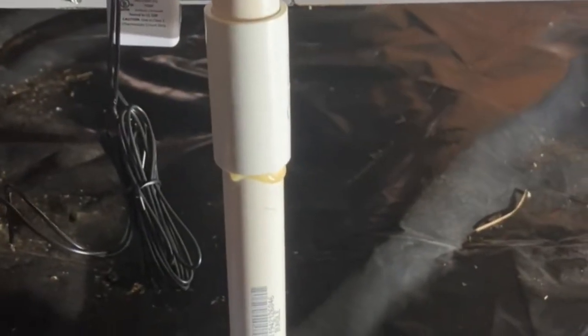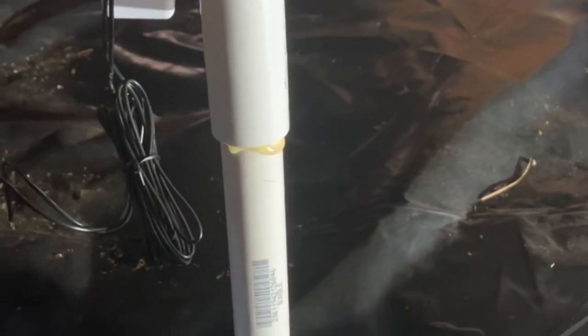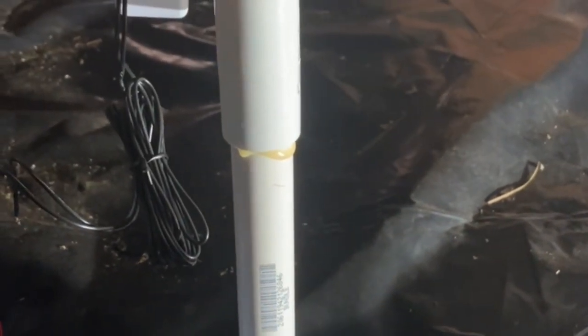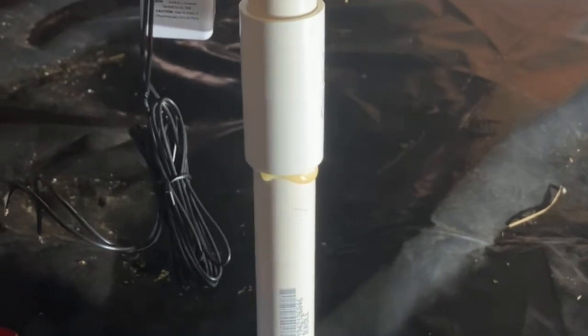Well, there's one. Gotta run the drain from there and hook the auxiliary switch up, and gotta hook the thermostat wires up too. Got the drain started in there. That's the cap right here. It's not glued in, it comes out for maintenance, unstopping drains, whatever.